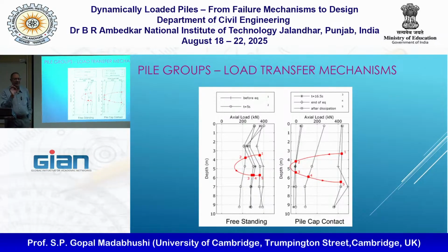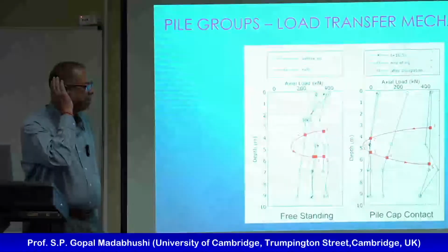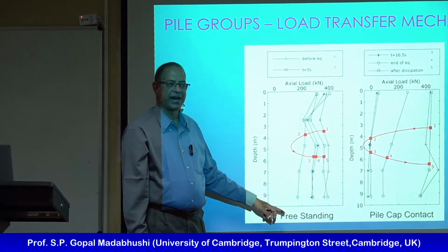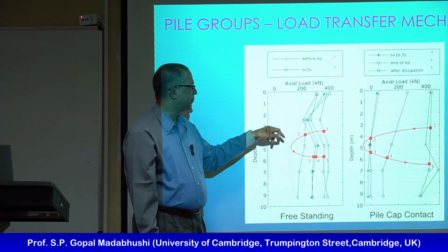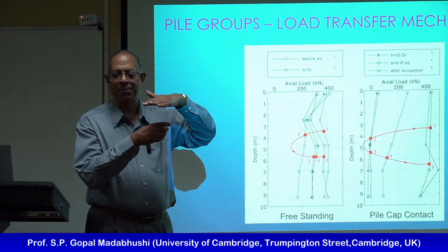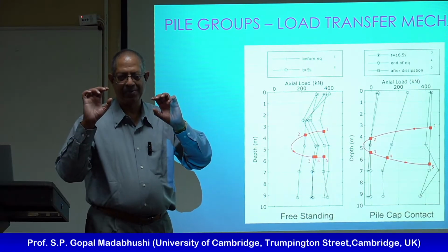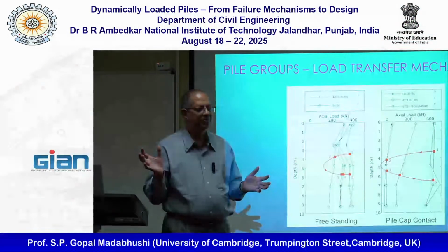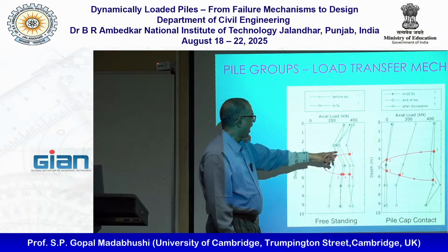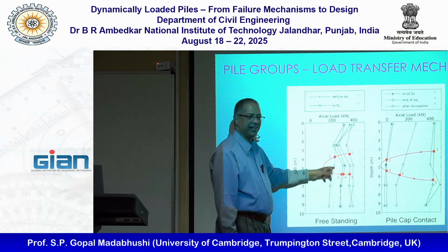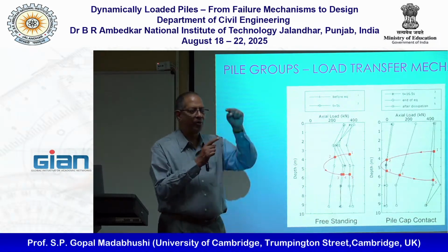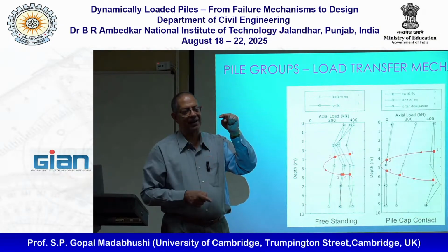And then the penny has dropped in our head. Basically, if my pile cap is not in contact with the ground during this particular earthquake, the total load being applied on the pile cap, somebody has to carry it, right? So this can only come down to 200 because that load has to be carried through all the elevations of the pile.